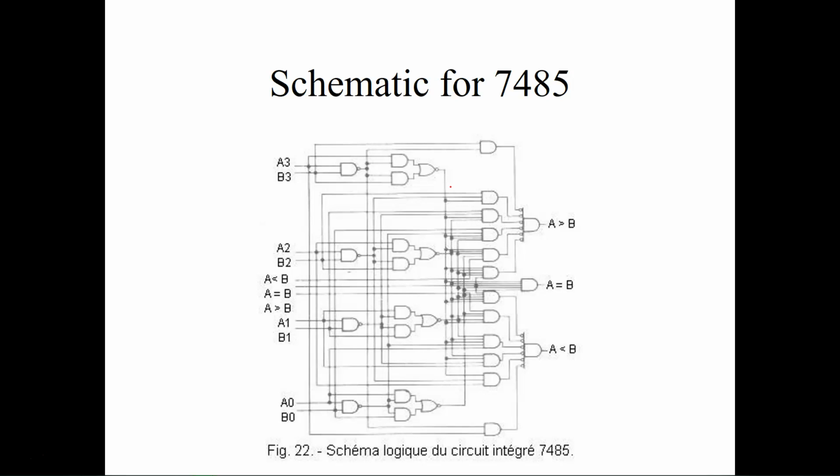Is it because one's high and one's low? Well, it's also because in the symbol itself, if it was an exclusive NOR, it'd have that little slash on the back end of it. That's what indicates an exclusive NOR. But this is just a NOR in and of itself, which means that any inputs you put into it are going to be negative on the output.